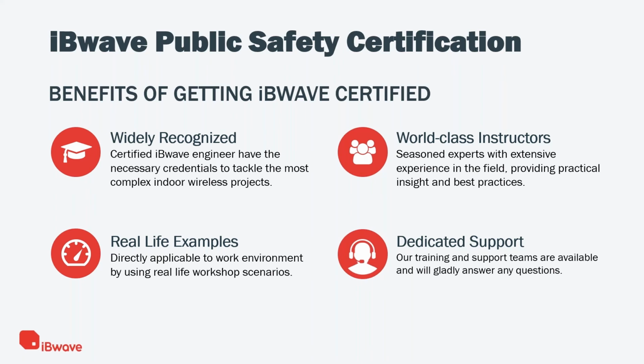And with the transition, you're still seeing a lot of public safety using radio, slowly transitioning to FirstNet or other competitive networks that provide data. So I think in the future there are probably going to be other requirements related to signal-to-noise ratio, because you could correlate it to data speeds. But that's today: that's how you measure existing coverage, using a third-party collection tool, and then post-deployment you're doing a grid test.